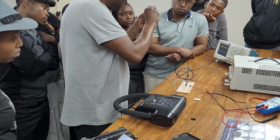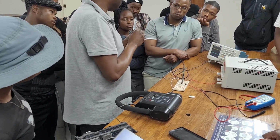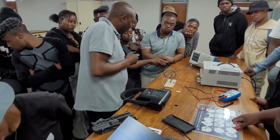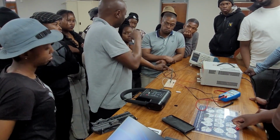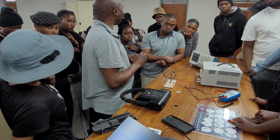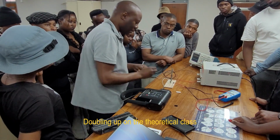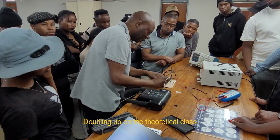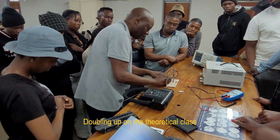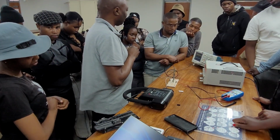So by putting this back, I'm providing a path for AC signals. The AC signals from my voice, alternating, very tiny, will now have a path to ground in the emitter, okay? Which is just basically connecting it to the emitter. And the gain is back, okay?